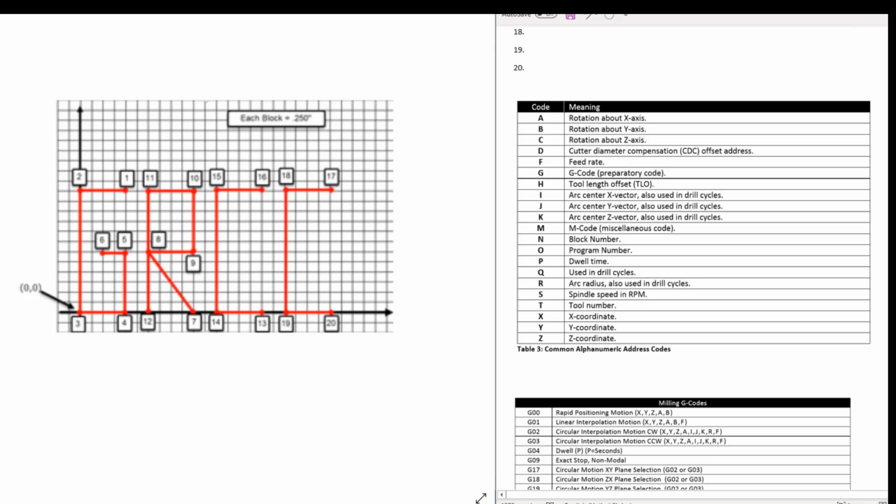And then our last set of commands are what I like to call the letter commands, and the letter commands are signal commands. You are sending a signal to the machine that says, hey, get ready to perform a movement, or get ready to record a number. So for example, your X, Y, and Z, which are your three primary coordinates, are letters. X axis, Y axis, Z axis.